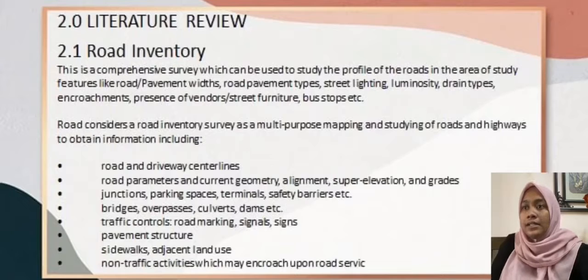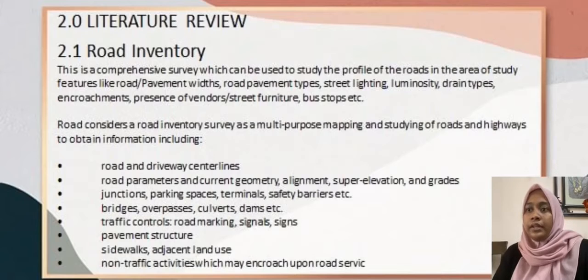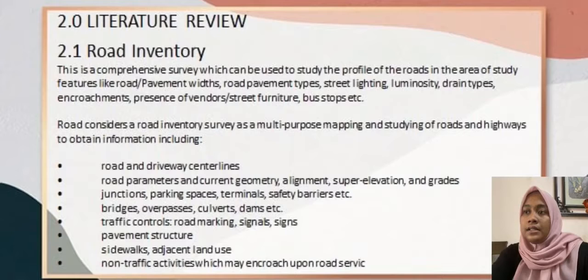A road inventory survey is considered a multi-purpose mapping and study of roads and highways to obtain information including road and driveway centerline, road parameters and current geometry alignment, superelevation and grades, junction, parking, surface, terminal, safety barrier, bridge overpasses, culvert, traffic control, road marking, signal, sign, pavement structure, sidewalk, adjacent land use, and non-traffic activities which may encroach upon the road service.